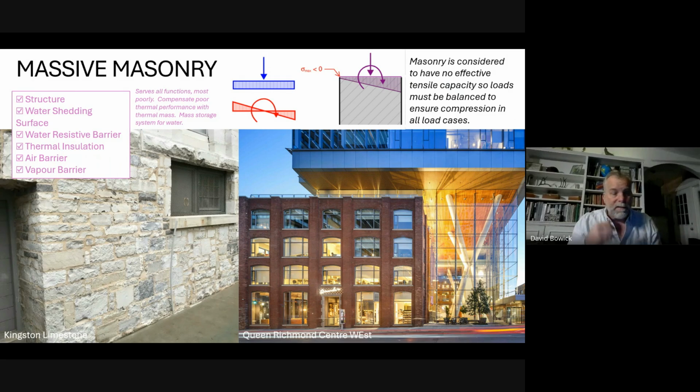But you take those bricks, you put them through multiple freeze-thaw cycles. There's not a bad chance that a crack is going to propagate. And 10 years down the road, you're going to pick up those 2 bricks and they're just going to pull apart. So we consider masonry to have 0 tensile strength. If you remember from structures, when a beam is bending, you have tension on the bottom and compression on the top. It's pulling on the bottom, compressing on the top. That's beam behavior. So if you have bending, you have tension.